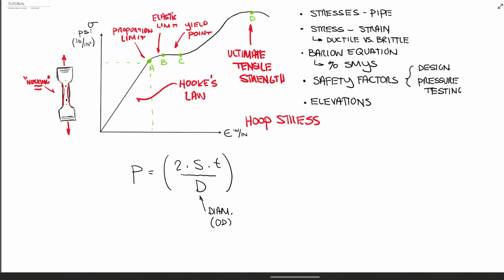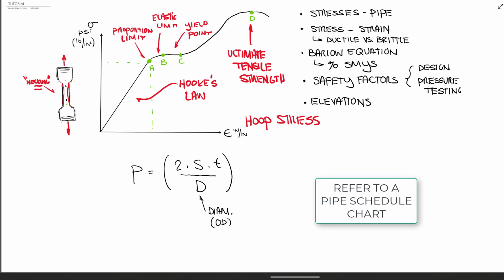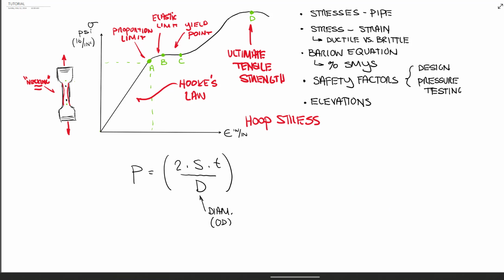Essentially from 1 inch all the way up to 12, or I don't even know if they make 13-inch piping, but up until you hit 14, the outside diameter is not actually, 2-inch piping is not 2 inches in outside diameter. 12-inch piping is 12 3/4. When you hit 14-inch, then it's a 1-for-1. So 14-inch piping, the outside diameter is actually 14. 16 inches, the OD is actually 16.